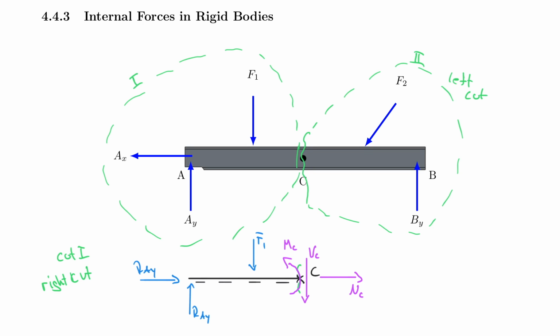And hopefully you are looking at this right now and you say, this is actually an easy problem for me now because I can already calculate these forces. This looks exactly like what I've done when I solved cantilever problems. So when you were solving cantilever problems, all the forces were given to you except the force at the cantilever. And what forces did the cantilever balance? It balanced a vertical force, it balanced a horizontal force, and it balanced a moment. And this is exactly the same.